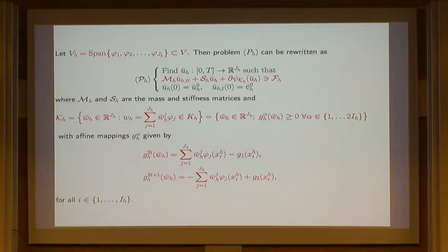As long as you have a free flight without contact, you can get any order of convergence if you choose an appropriate integration rule for the time discretization. But when you have the first contact, then you lose everything. And there is no need in choosing a better time integrator than this first order integration in some sense, since the theta method is, except for the value of theta equal to 1 over 2, a first order method for differential systems.